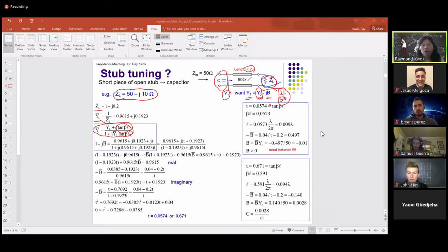You put 50 ohms here, you don't see 50 ohms unless the transmission line is also 50 ohms. Remember all those calculations in the transmission line chapter. The Z in is not constant, it depends on beta L, on L. So that's exactly what we're doing.